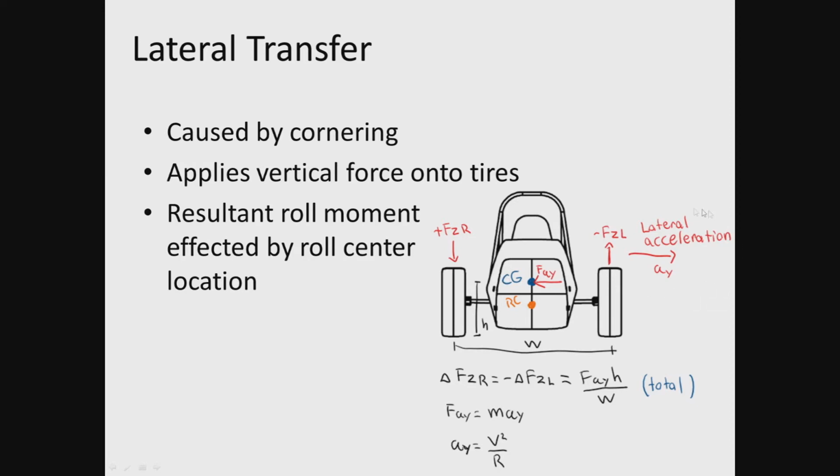We're now concerned about the lateral acceleration component, which is the acceleration of the car towards the inside of the turn radius. So if you're taking a right-hand corner, your car has to accelerate in the right direction. You're seeing a reaction force in the left direction, and you're going to transfer weight to the left side of the car. Remember to think of that in terms of reaction forces, not the acceleration of the car itself.